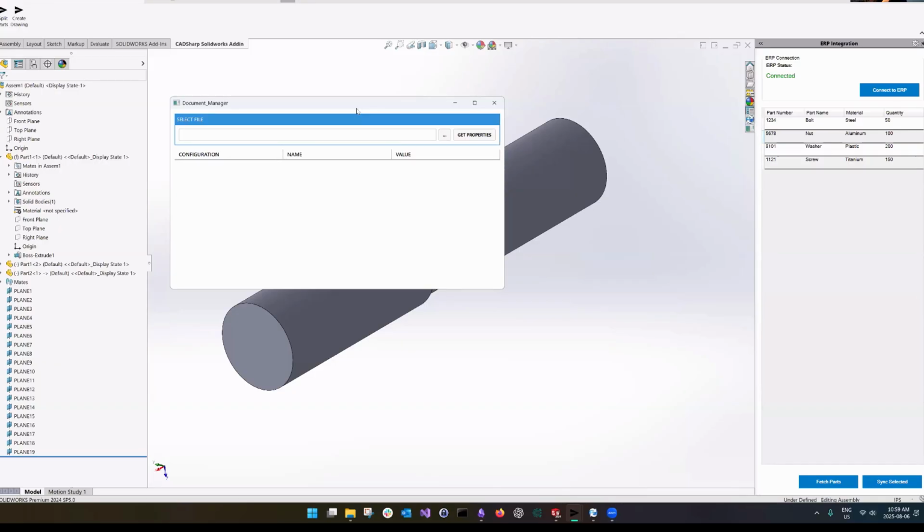So the big bottleneck in automation or doing it manually is often opening the file, rebuilding it. The making changes part goes pretty quick, and then rebuilding it and closing it again. If you've opened a large SOLIDWORKS file before, I'm sure you're familiar with how long it can take. And even if it's only taken a few seconds, if you multiply that few seconds by 10,000 files they need to process, well, you're into hours and even days in some cases. So that's where the Document Manager API comes in. Like I said, it can read and write to SOLIDWORKS files without opening them. So it gives us an interface basically directly to the file itself.